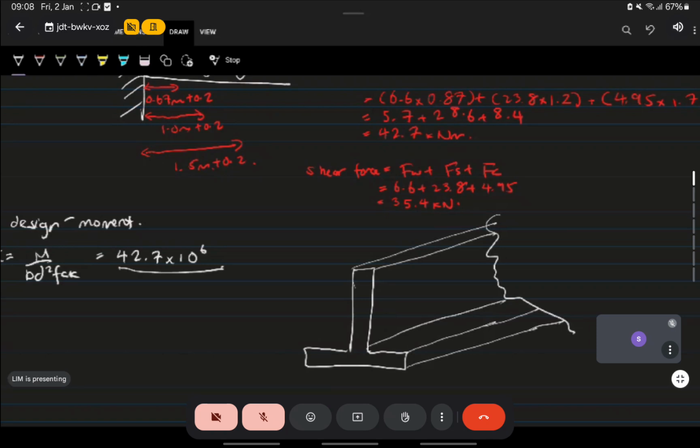So in other words, you design it like a slab. A slab is continuous as well. So the way you design it is like a slab. You design for a 1 meter segment. Whatever reinforcement you have, you spread it all over. Every meter you have the same reinforcement. So the b you take 1,000, 1 meter.